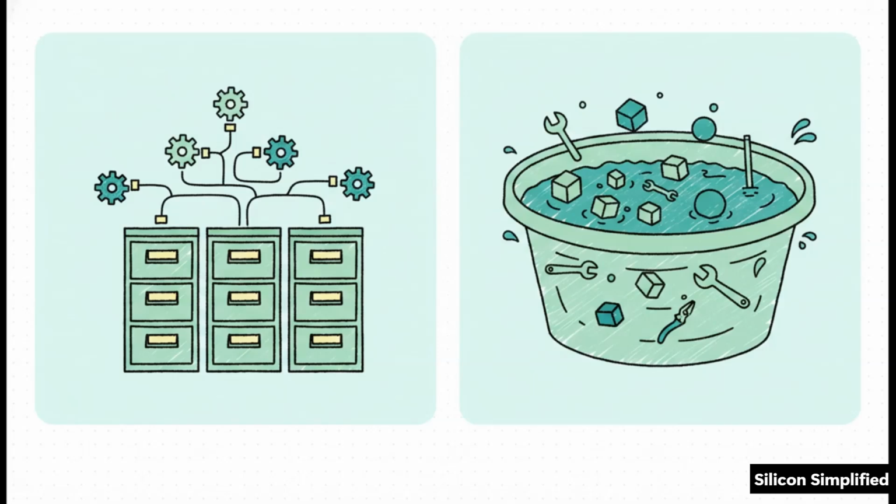You can retrieve items by name or type, and it essentially operates like a giant global pool. But layered right on top of that is the uvm_config_db. This one provides a much simpler, structured interface specifically designed for managing component-level configurations. Because it actually respects the component hierarchy, the config database is the heavily recommended tool for tasks like passing virtual interfaces from the DUT all the way down into your test environment.